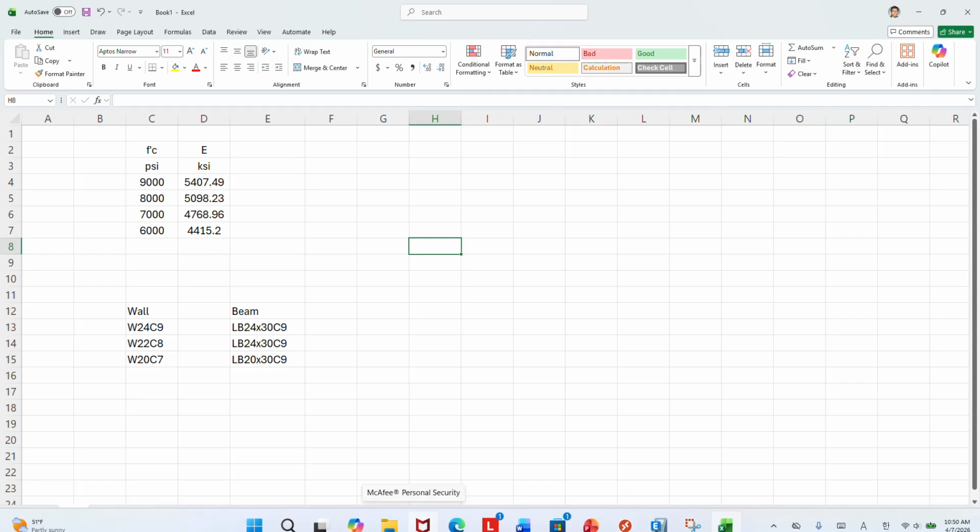So everybody has a 3D model ready, right? Wind load is ready, and your wall currently is everything 12 inches thick. If you already assigned something? Ours is 18 inches. Okay, so we can start. First of all, the first run is based upon the current wind load, service wind load. We're going to run that model. That's your first original model. You prepare the Excel spreadsheet for how much deflection we get. Okay, so that is the first run.